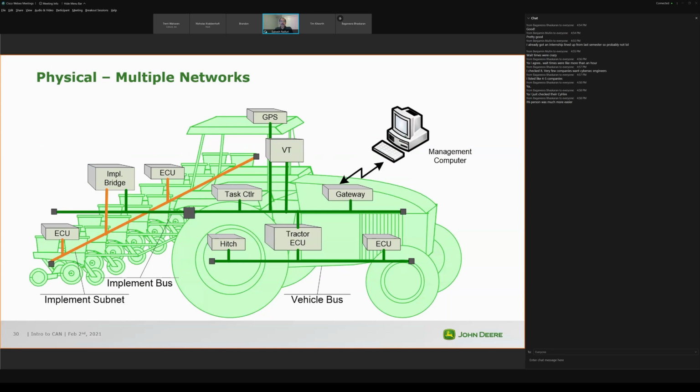So when we say a higher baud rate, within John Deere, we chose to stay with 2 megabaud. So the CAN-FD frame with the flex rate, in John Deere, we decided to go with 500K and 2 megabaud, and that is the standard that we chose within John Deere. And follow-up is network security. But if you have any questions on the hardware side of it.